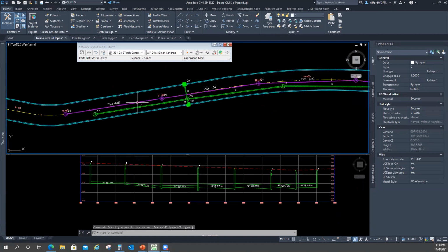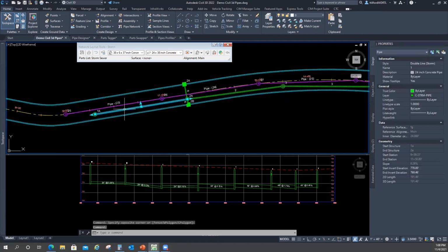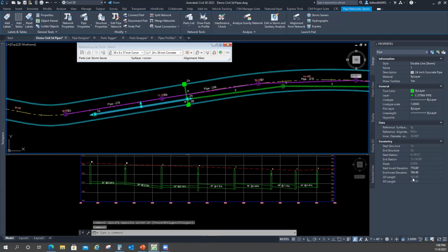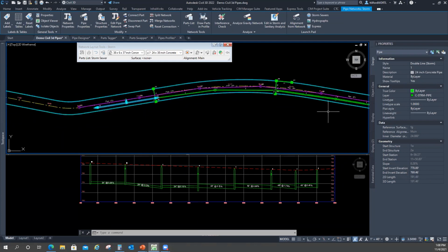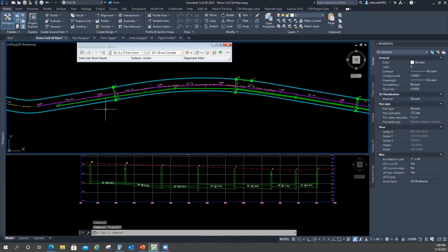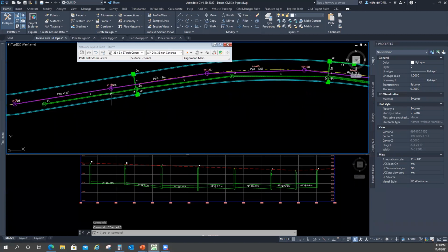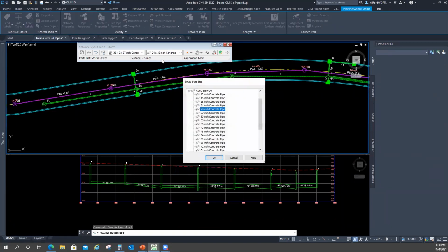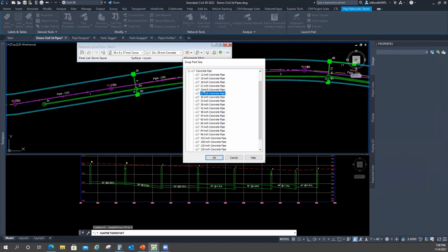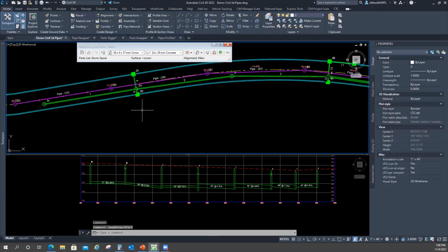How do we edit pipes now? If I have to edit a pipe, I have to come over here, get the value, interpolate the distance, and then apply the slope. How do I swap parts? If I swap a part, I have to right-click, swap the part, choose the new part and hit OK.